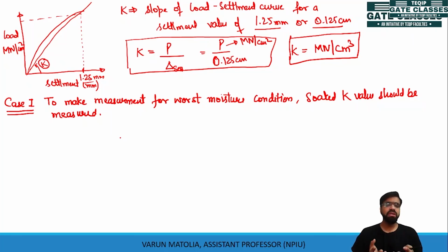There may be a condition when the subgrade is completely soaked. So to replicate that condition, we should measure soaked K value.